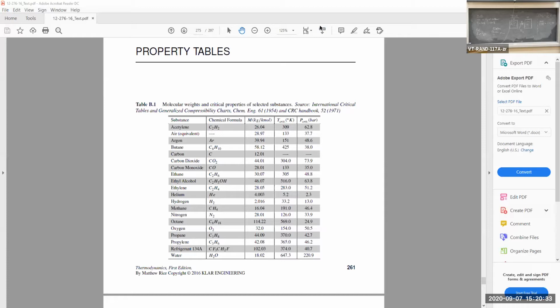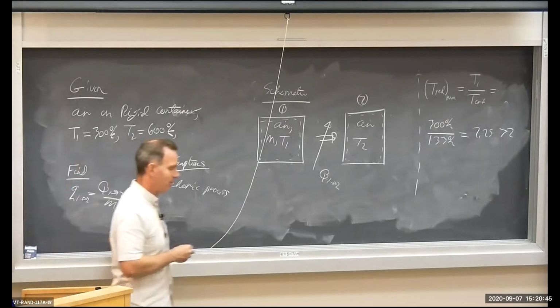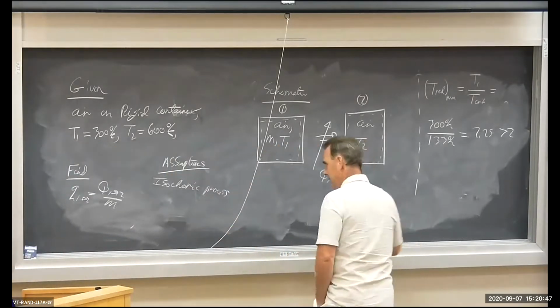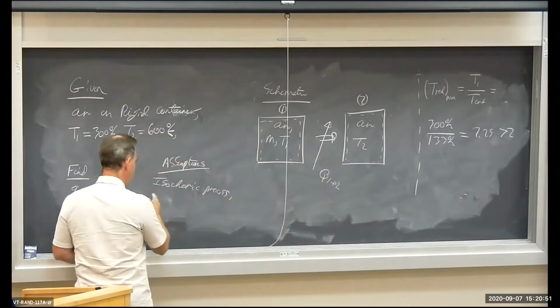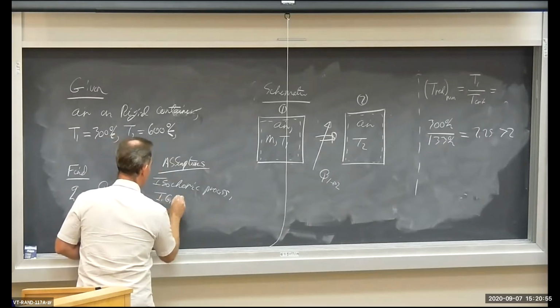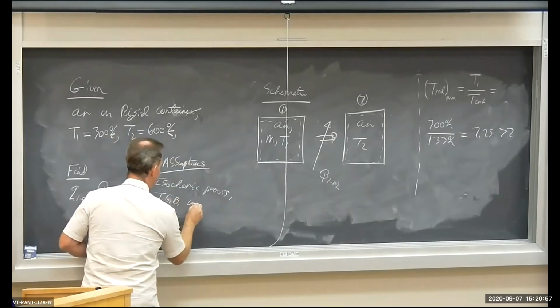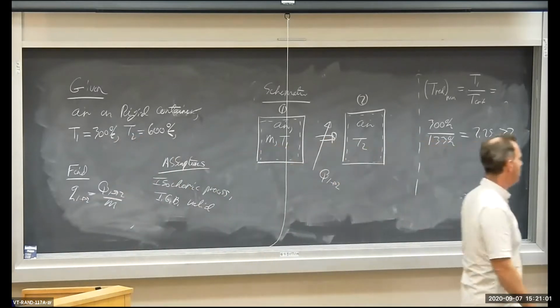Because the critical pressure is so high, for most workable pressures it's quite plausible from an engineering standpoint that our reduced pressure is going to be less than 0.2. So I'm not going to make too much of a song and dance out of it. I'm just going to write here under my assumptions, IGB valid. We can treat the air as an ideal gas, IGB valid, okay?